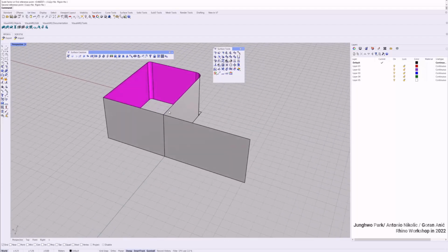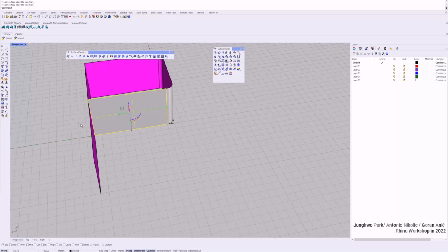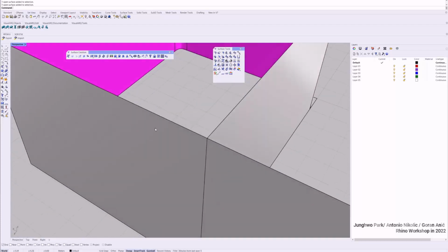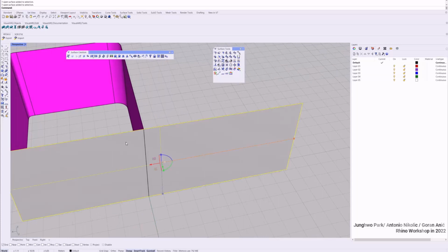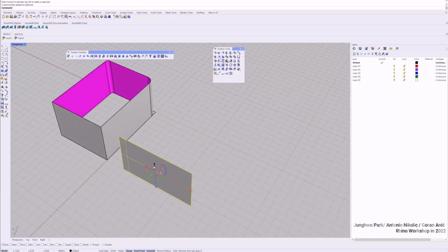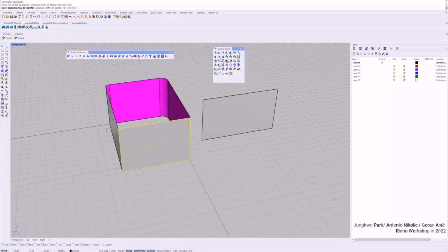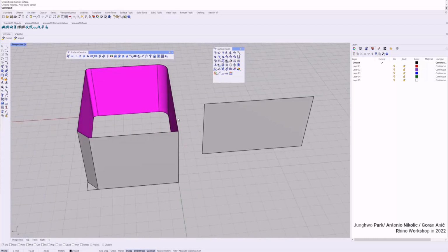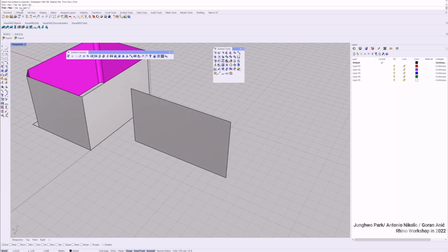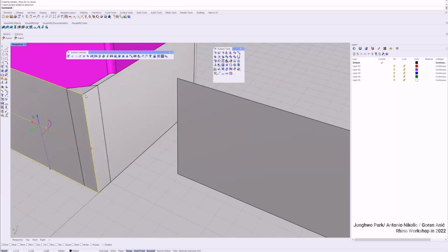When you have surfaces which intersect each other, for instance here there are intersecting edges, you can split, type Split like a line. You can split this surface against that one, and you get the split surface. It's very simple. And the Chamfer Surface is just simple. You can do the chamfer. I think you can set the distance of the chamfer, or extend it, trim or not. You can choose. If I do trim, I don't know what result we get, but let's see. Basically, you get the chamfer but not trimmed surface.